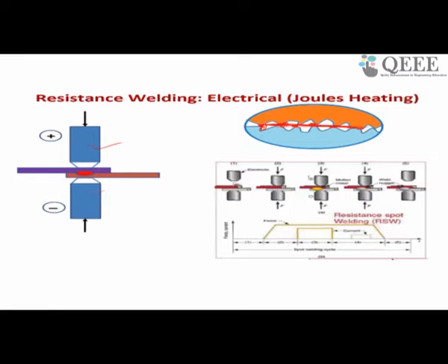What happens actually in electrical spot welding? In resistance welding you place the workpiece in this fashion. Then you place electrode 1 and electrode 2 like this. Then in the second step you apply force. You have placed the two electrodes together and applied force. You can see the plot of force versus spot welding cycle time, force versus time. After some time you apply force, so in this stage you have applied force. Then here you have to supply current also. So this is for force and this is for current. When the force is high enough, what is the objective of force?